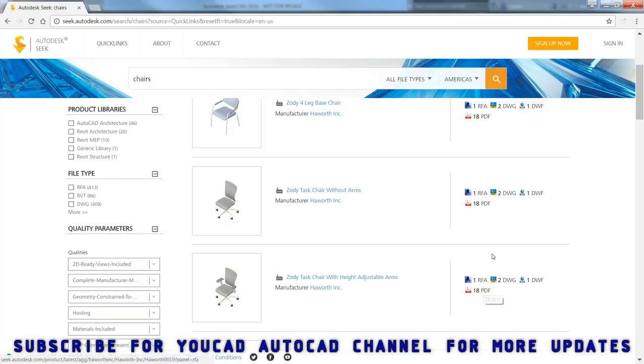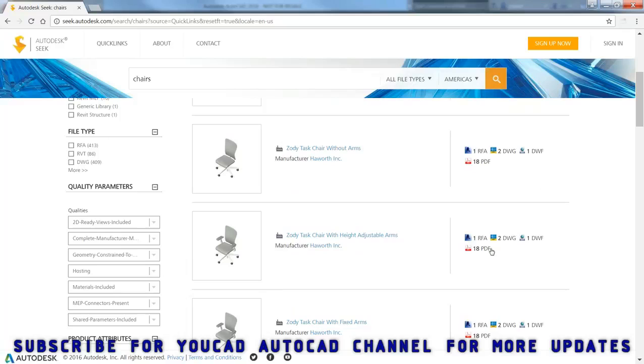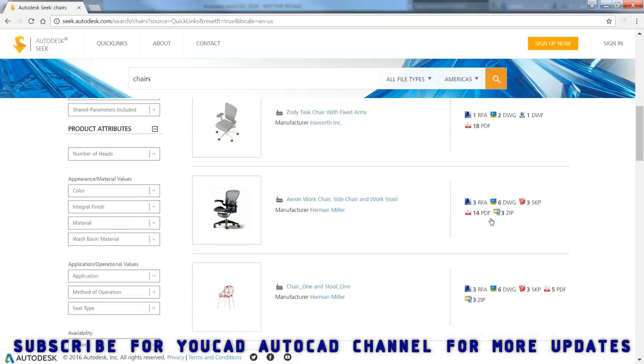And of course PDFs. Now, with AutoCAD 2017 having the new ability to take PDFs that are attached and extract the geometry from them, turning it into editable geometry, all these PDFs available on the Seek website become that much more useful. In most cases you'll find a DWG too, but if you find one that doesn't have an AutoCAD DWG but does have a PDF, you can just grab the PDF, import it into AutoCAD 2017 or newer versions, and turn it into editable geometry.